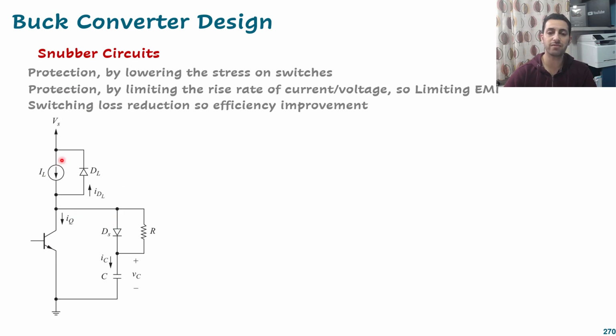I think if we have an inductive load here, once I switch off that transistor, that inductive load will try to push that current to that node here, but because that is off, it will try to raise the voltage until this switch turns on, and then that will consume the current or let the current flow. But at that moment exactly, the voltage here has a little bit of a rise on that switch.